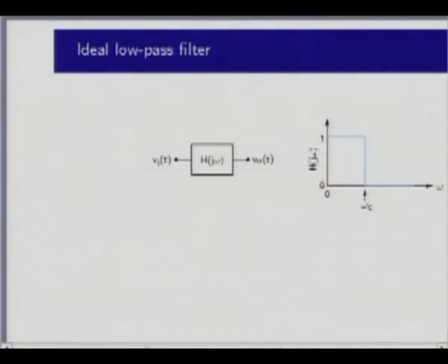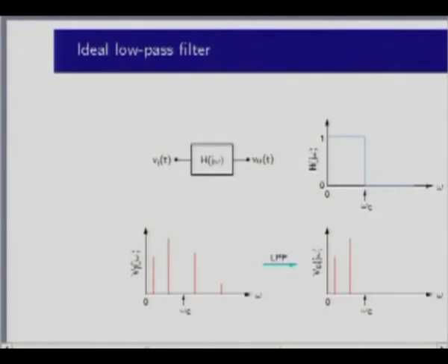And before we actually go to op amp filters, it is good to explain what ideal filters look like. Okay. So an ideal filter actually looks like a gain of 1, that is pass, and a very sharp, infinitely fast fall, and then 0. That is what an ideal low pass filter would look like. And here is an illustration of what it does.